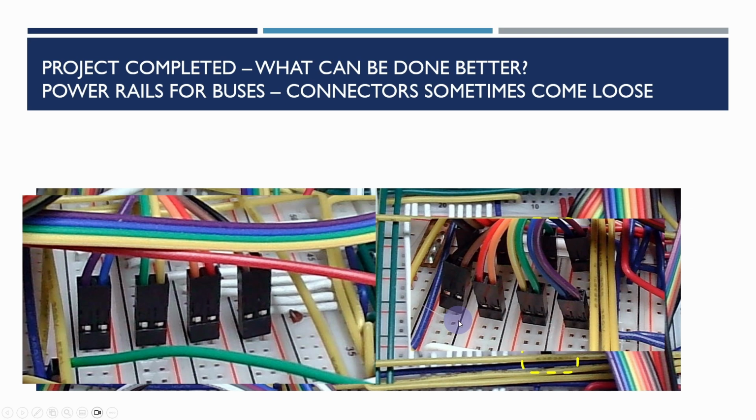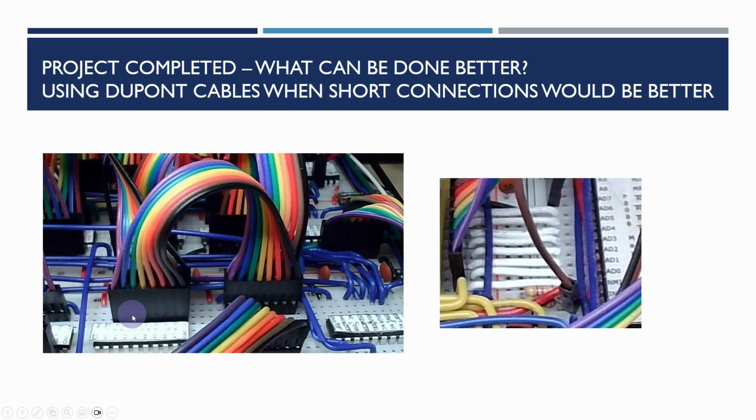So I wanted to find a better way of using these buses really for doing the address, data and control bus signals. And also after the tip, using these Dupont cables and the 8-way connectors. So you can see here that there's an 8-way connection on the CGA card between 2 bits here. In hindsight, as I was pulling the 6809 project apart, as I was actually pulling these types of wires out on the right here between things, it became clear these are quite sturdy and won't come loose at all. And so I think perhaps in hindsight, I overused these Dupont cables.